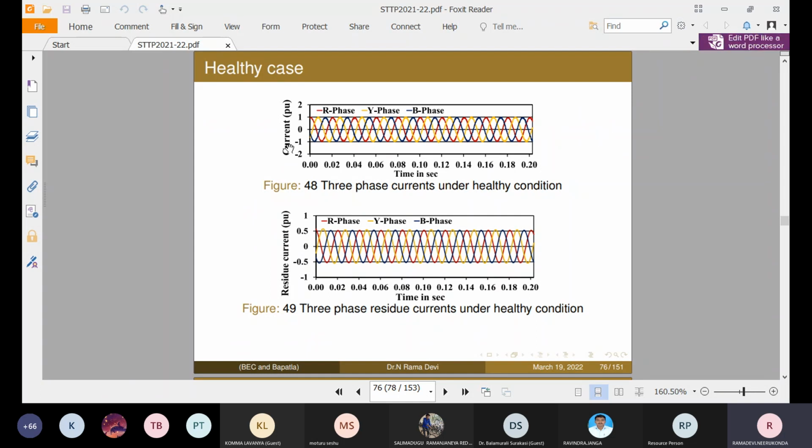What we require for the reconstruction is the extraction of features of the three-phase currents. Here we look at the current signal, which is corrupted with certain noise. We eliminate that noise by making use of the SWT technique, and with the help of that, we reconstruct the signal.